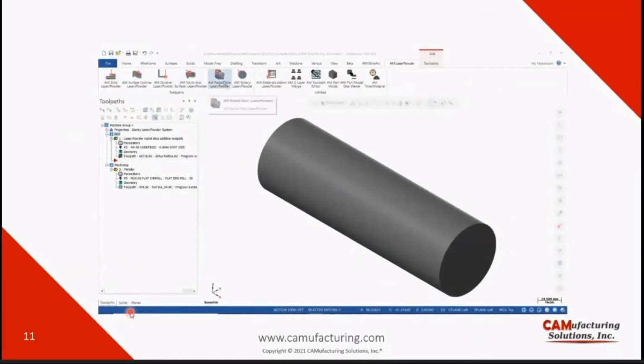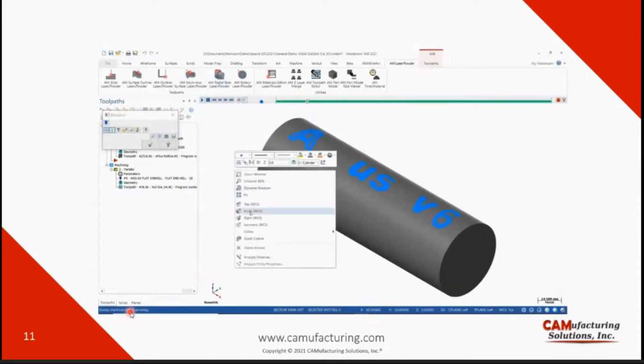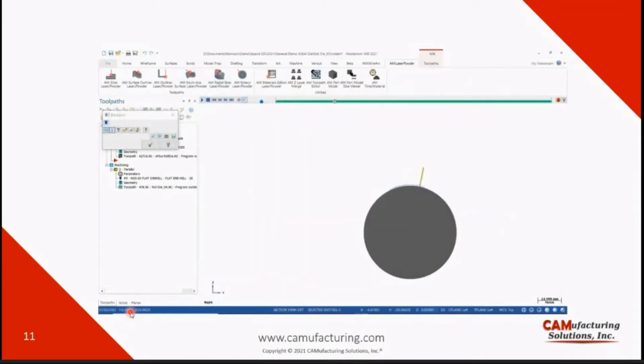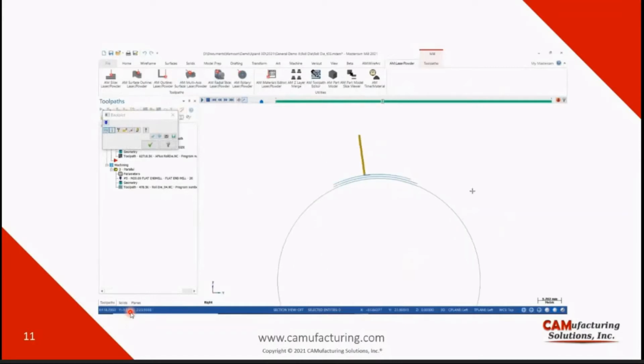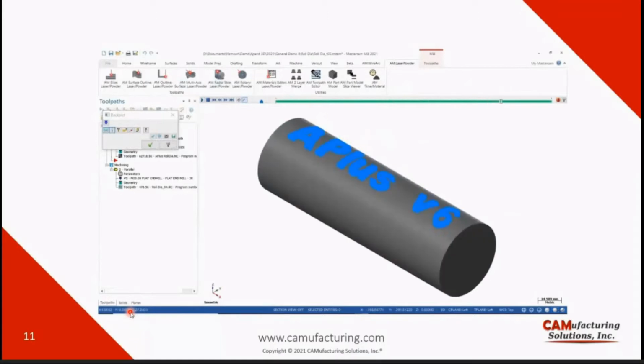So this is the AM radial slice toolpath which you use there. I'm going to show you the back plot. I'm going to show you the right view to see how it is basically sliced radially instead of planar. So this is the first slice, second slice, and third slice. If I show you the isometric view, you can see that it is basically building your parts on a radial basis.